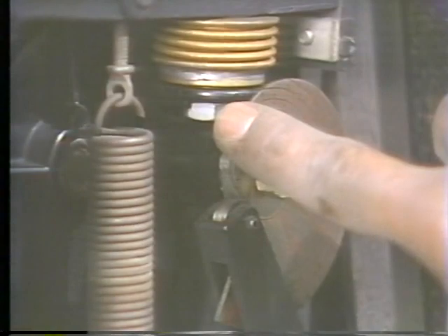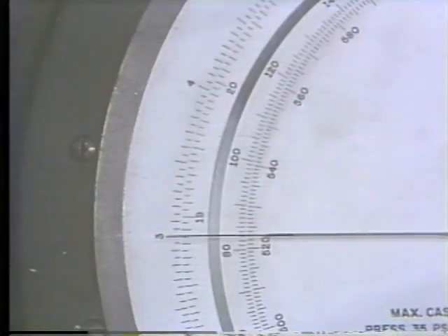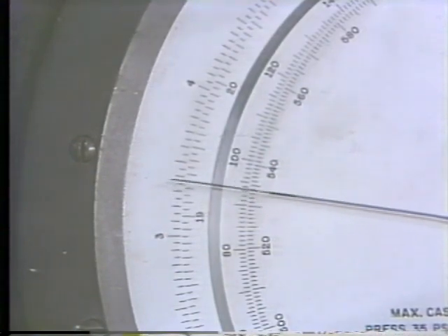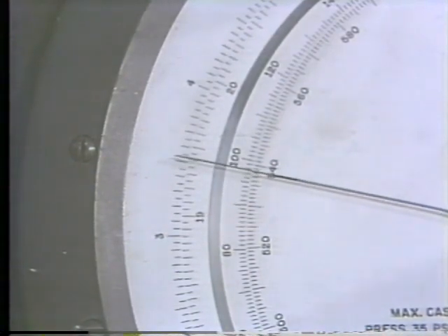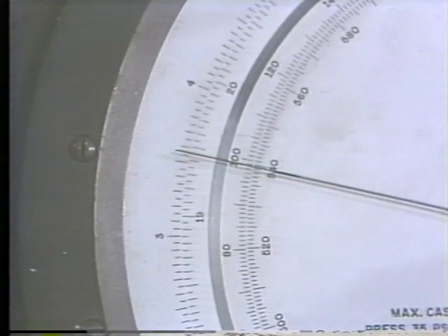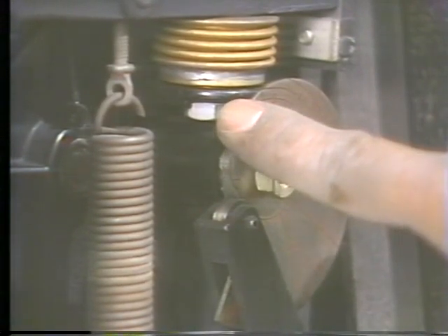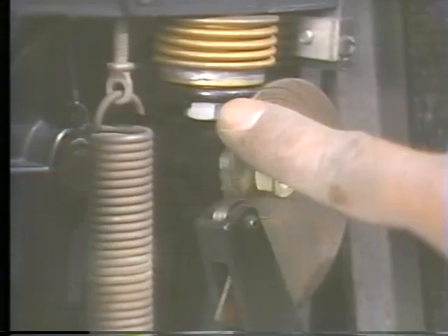Then with his finger lightly touching the edge of the cam, the technician increases the loading pressure just slightly until the manual loader indicates 3.5 psi. At this pressure, the technician should be able to feel the cam move just slightly, indicating that the piston in the actuator is beginning to move away from the shut position, partially opening the louvers.